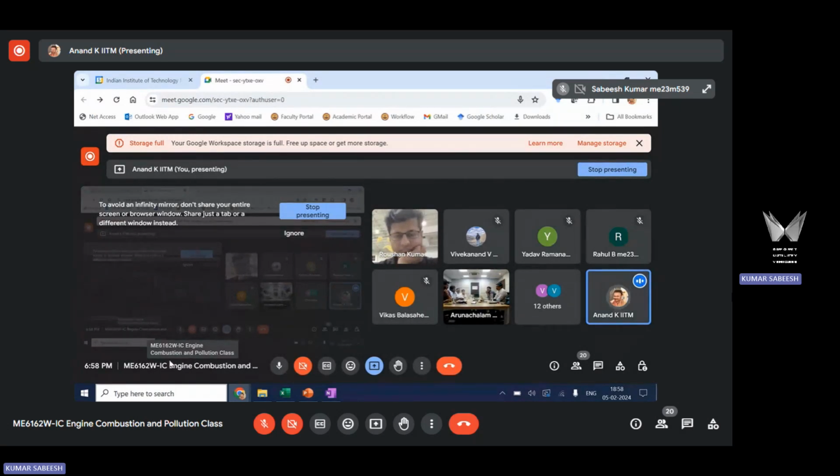So it's time up. You have one more. Yes, sir. Sir, this sulfur content you have mentioned, for diesel, say BS4, the energy will differ with different sulfur content, fuel heating value. Sulfur has no role on the heating value. Heating value primarily is dependent on the carbon and hydrogen content. See, the sulfur value you're talking about is 10 milligram per kg, right? And the majority of the elements are carbon, 84% and 14% hydrogen. So it is almost 98% of the total fuel composition. Sulfur is coming as a trace element.